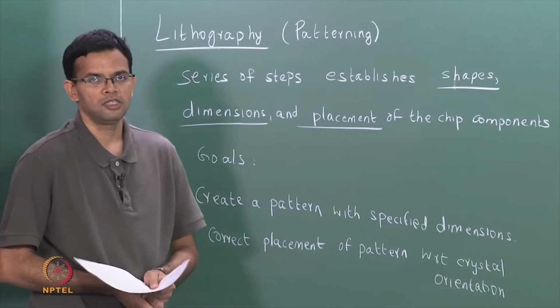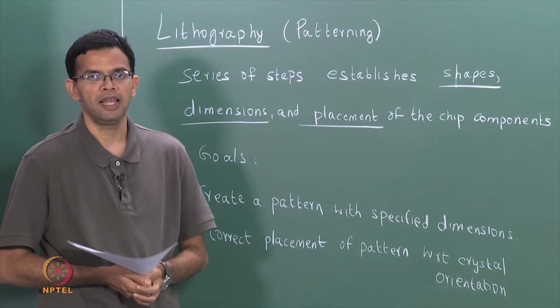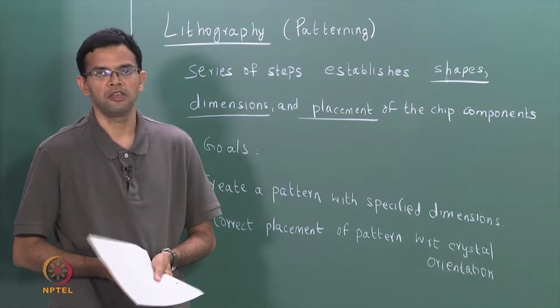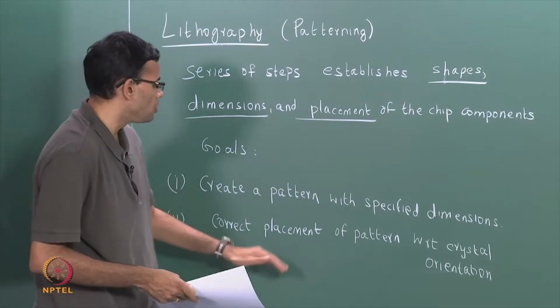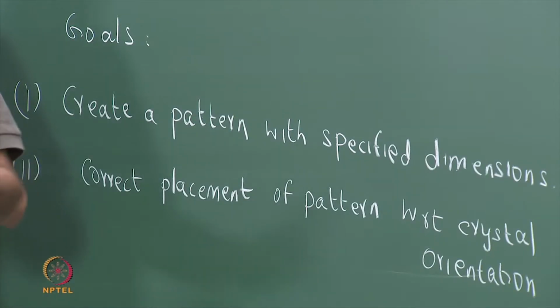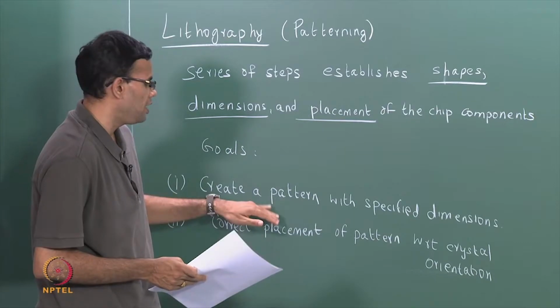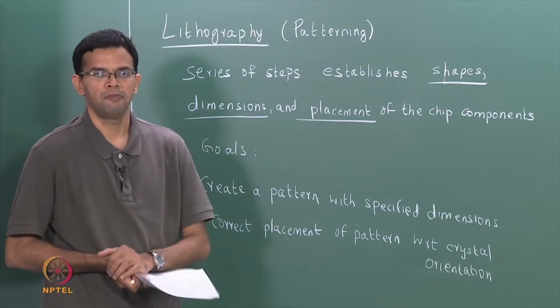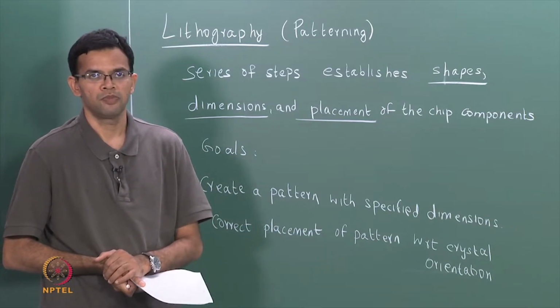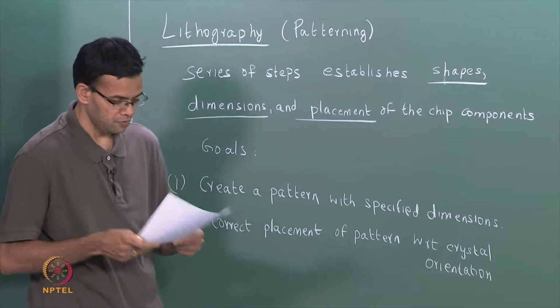This is because typically we will have multiple layers or multiple patterns for a given chip, so all of those patterns have to be aligned to each other and also aligned to the base wafer. So both creating the pattern and placing the pattern are important goals in lithography.